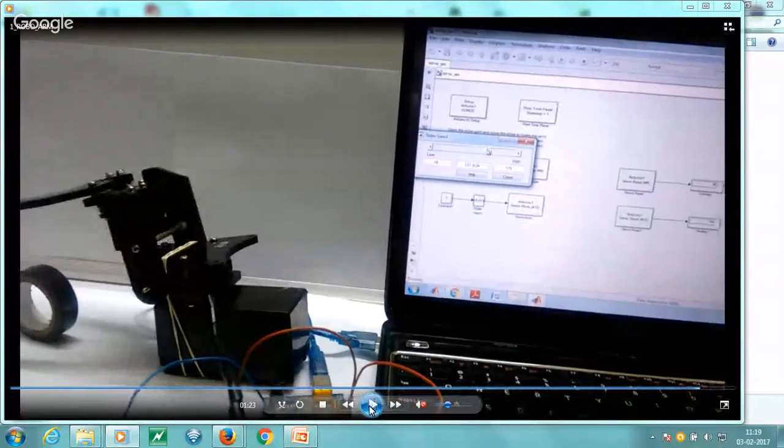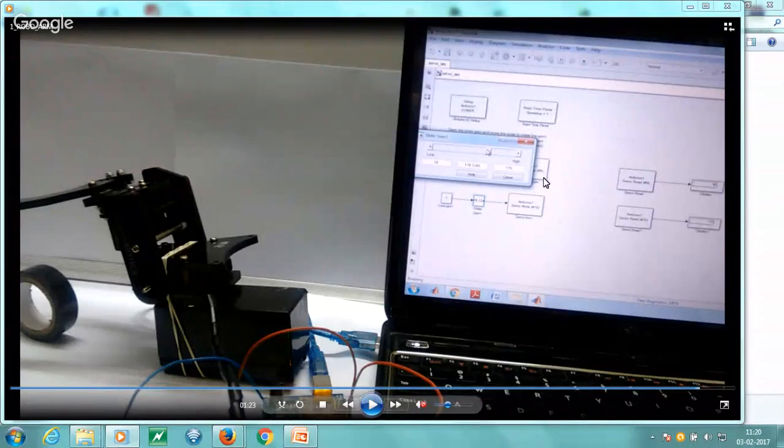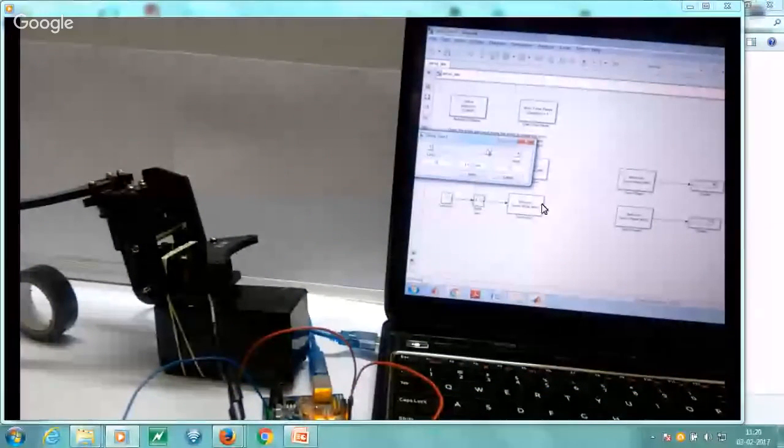And for that purpose, if you want to do some inverter applications, we will do the PWM pulses or different types of pulses. We will make a diagram in this window and we will send it with the help of some digital input output pins or PWM pins. So we can use optocouplers, MOSFET driver ICs, whatever you do on your Simulink platform, you can easily connect. Just use these two blocks on this Arduino platform and use your Arduino digital pins for real-time applications. Okay, fine. So this is very useful for your engineering research, and for implementation purposes, you can easily do it.